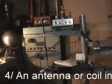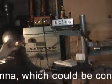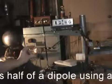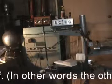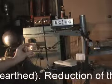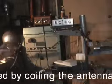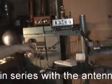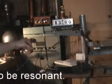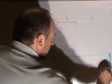4. An antenna in the form of a quarter wave monopole antenna, which could be considered as half of a dipole using a ground plane as the image of the other half. In other words, the other end is earthed. Reduction of the length of the aerial could be achieved by coiling the antenna, which becomes an inductor or loading coil in series with the antenna tuned to be resonant. Yes, it works as well. This demonstration relies on one dipole.